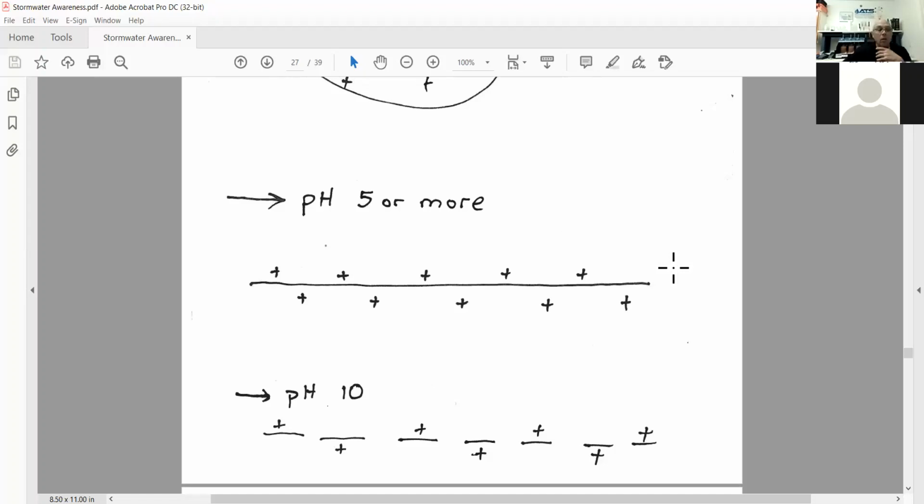All right, so now it comes down to, I'm going to stop sharing. How is coagulant dose determined on any given water sample? Coagulant determination happens in two places: one in the laboratory on a lab bench, and then in the field inside a control unit. For the lab bench I've got set up here, you grab 5 to 10 gallons of actual site water sample, or you produce simulated stormwater using distilled water and actual site soil samples.